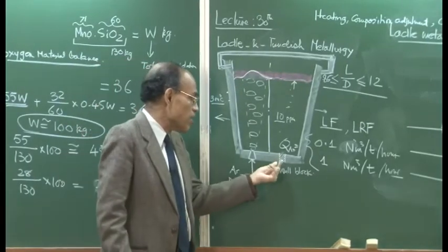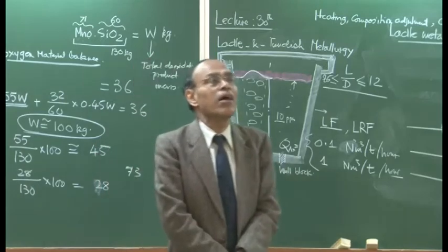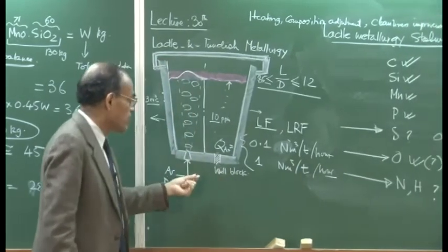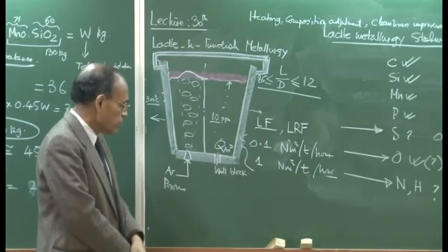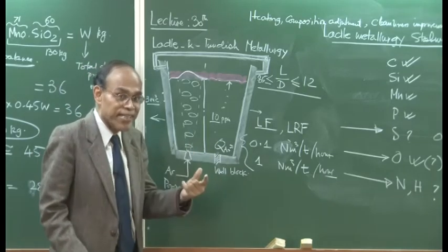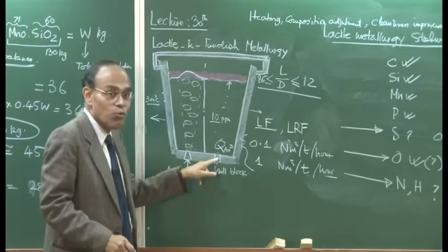Well blocks are closed with some refractory material, which tends to get sintered, and as for the slide gate, they are not expected to get sintered, because if they get sintered, then the removal is going to be very difficult.